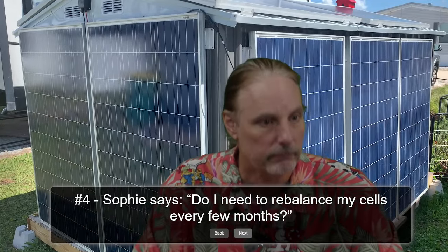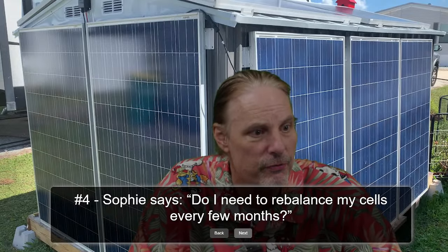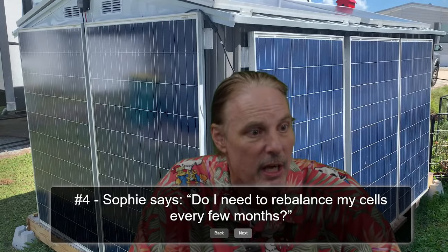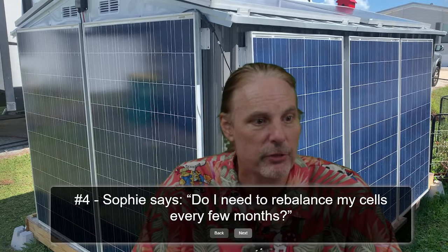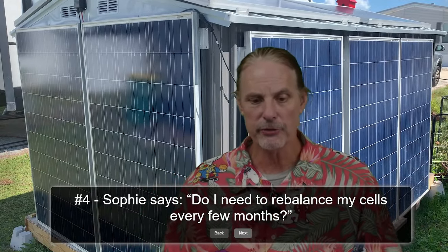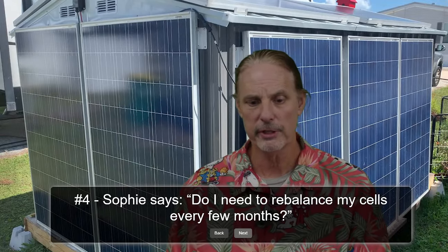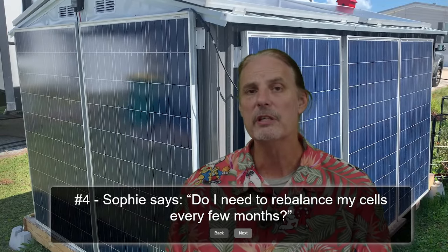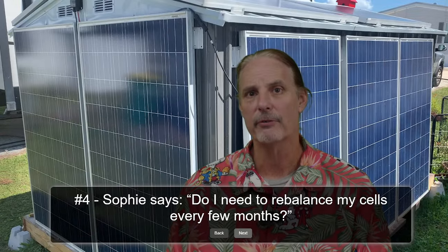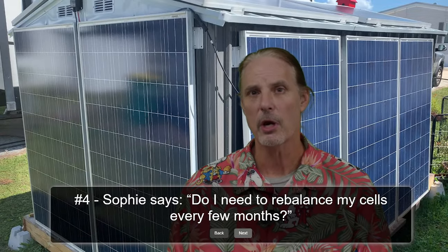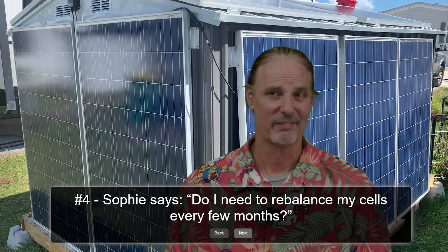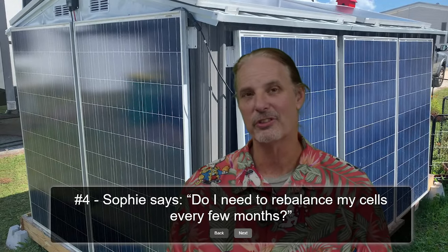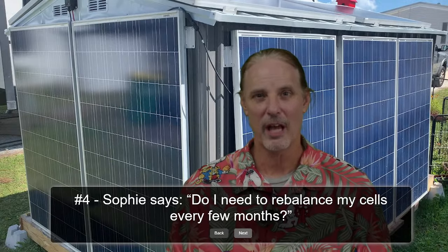Okay. Number 4, Sophie asks, do I need to rebalance my cells every few months? The short answer is yes, you do need to rebalance your battery every few months. As we stated before, the BMS state of charge is most likely, to a certain extent, highly unreliable.